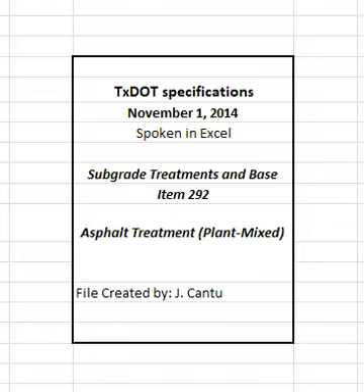Asphalt binder from RAP and RAS is designated as recycled asphalt binder. When RAP or RAS is used, calculate and ensure that the ratio of the recycled asphalt binder to total binder does not exceed the percentages shown in Table 2 during mixture design and production. During production, use a separate cold feed bin for each stockpile of RAP and RAS.